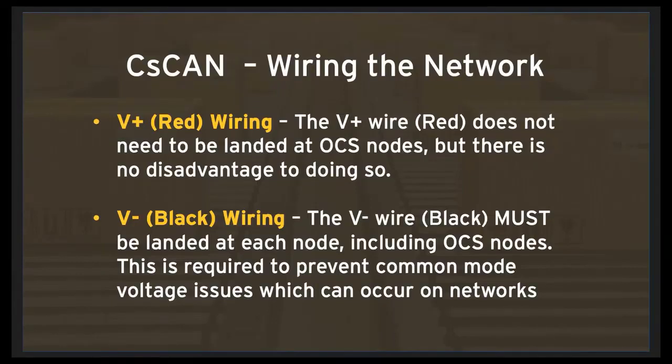So you must land the V- conductor on every node if you're installing the network, regardless of whether it's an OCS or an I/O block, whereas the V+ connector is technically optional, but we still recommend that you daisy chain it and make it complete through the network as well.